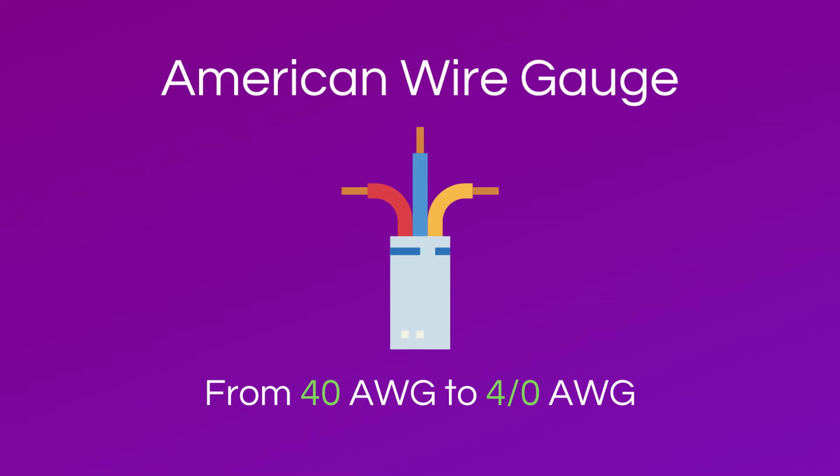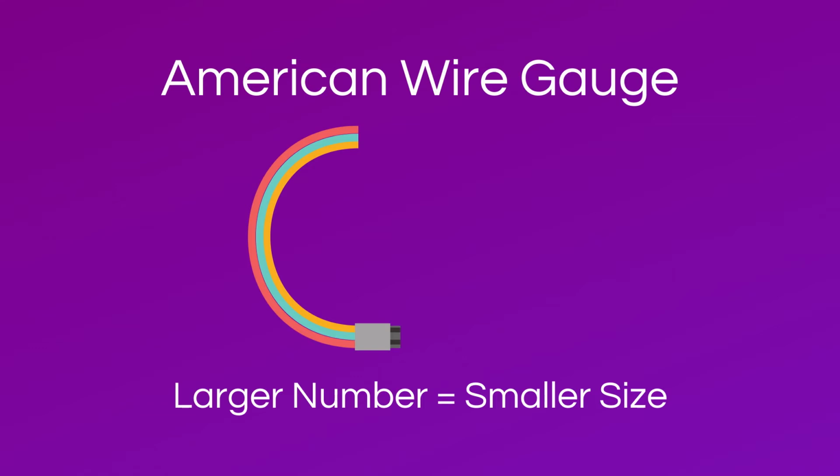Wire sizes go from 40 AWG to 4/0 AWG, and stranded wire may have the same AWG number but different strand count. The AWG numbering system is unique because the larger the number, the smaller the wire actually is. For example, a wire that is 30 AWG is smaller than a wire that is 10 AWG.